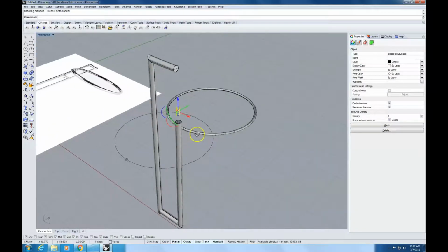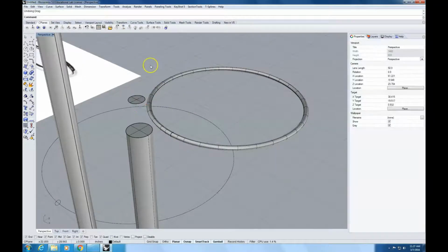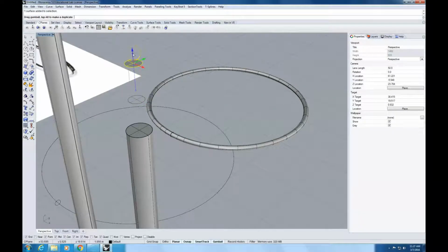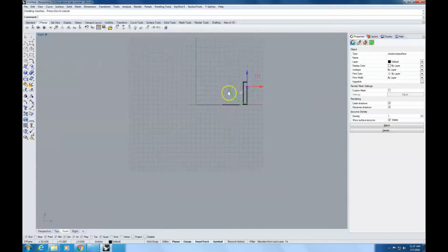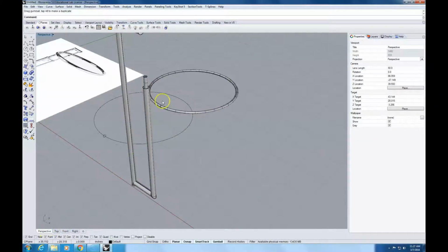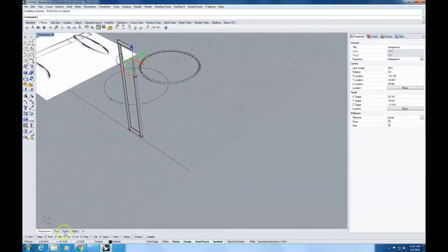Okay. So what I did was, and let me do it again, just because it's quirky. It all depends on what software; I'm thinking Illustrator right now. So when I select that, I'm going to start moving, and then I'm going to push down Control, and I don't know if you see a little line that pops up. So that's in extrusion mode. So now I actually made a physical 3D model. Which now I can kind of jam in here, and then go back to my perspective, and then pick that face and move it up.